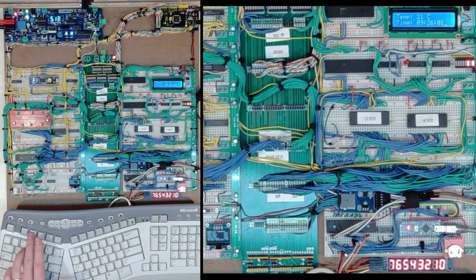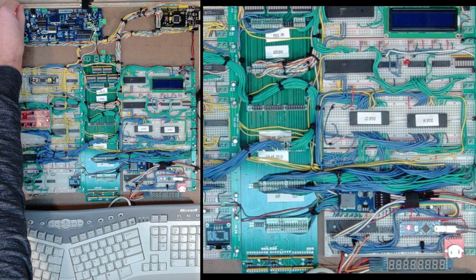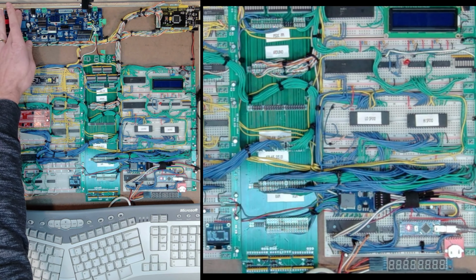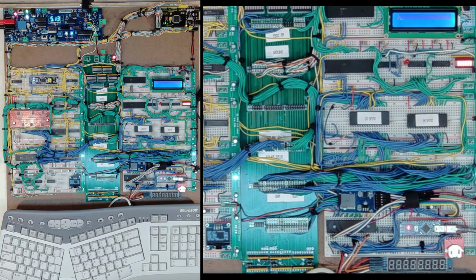And then I set up F2 just to test, and that should set the hour to 8. So if I hit that, you can see it set it, and now it's 8:26:06. And if I keep refreshing, I'll just see that I'm now counting up from 8:26. So that just helped me test and validate that I can set the time, I can read the time, and I can read the temperature. And at this point it says 8:26. If I turn off my main system, again, this is retaining power because of the Nano, and if I turn it back on, I should get that same 8:26 or 8:27, whatever it's at, pulled back up.